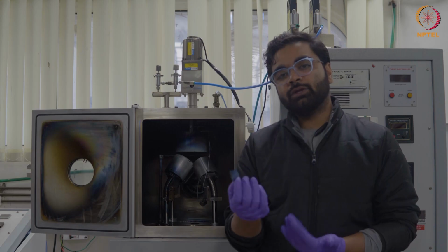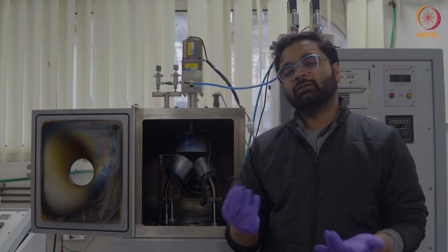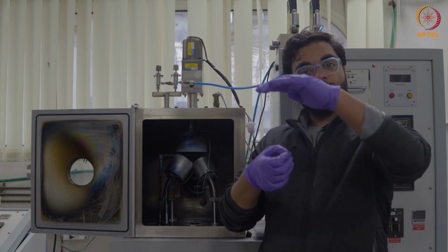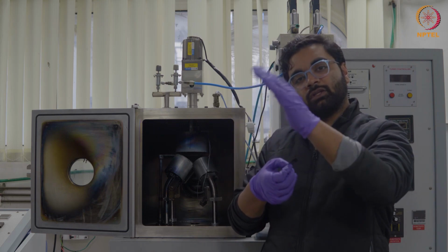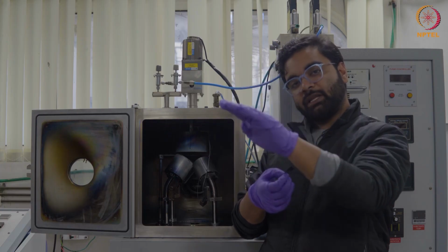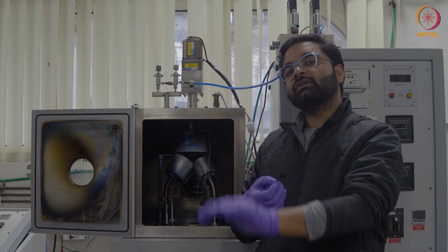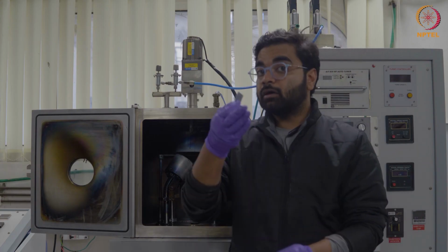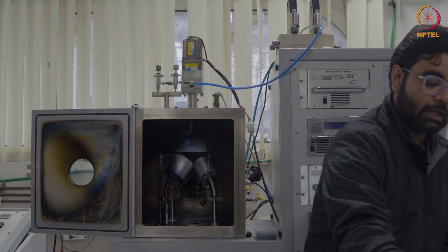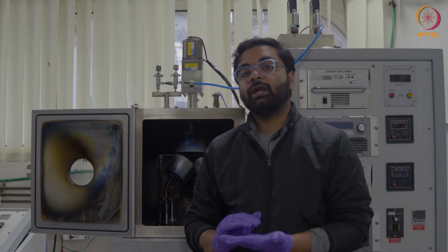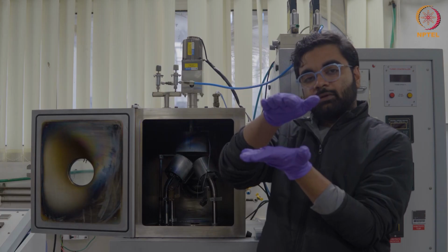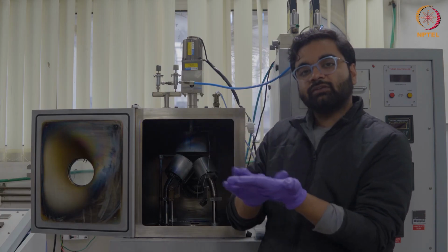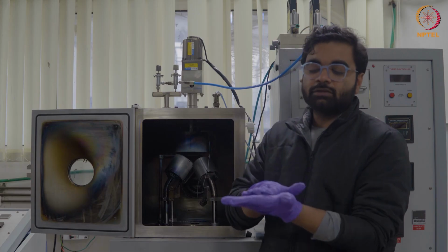You can do it on an ITO coated glass or a normal glass or any other solid substrate also, because the laser interaction is only happening between the first layer and the second layer. For the third layer, only because of the gas pressure, the material is getting transferred. Since the material is getting transferred, any kind of acceptor substrate can be used. But one important thing you have to take care of is that while doing the transfer onto the substrate, the material, once it's transferred from the surface and comes onto the base substrate, has to adhere to the surface. So for adhesion of the surface, what is happening?